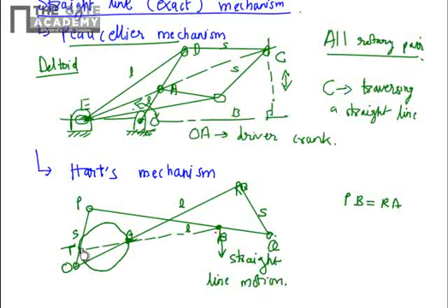So this link is a kinematic chain. You have to anchor it somewhere. So the point R in this chain, the joint R, is anchored to the ground. Okay, so it is such that there is a circle going from A. The A is going in a circle, and T, and it is touching that point T, and somewhere you will get a center of the circle C. So the motion of path B will be perpendicular to the line TC. So it is a somewhat complicated derivation you can see in a standard textbook.